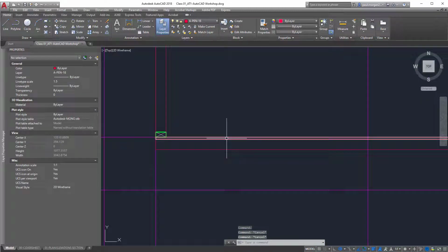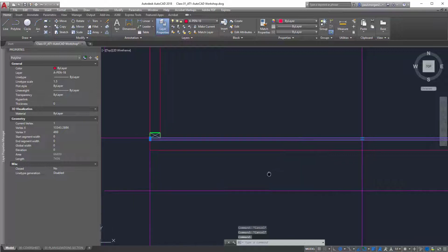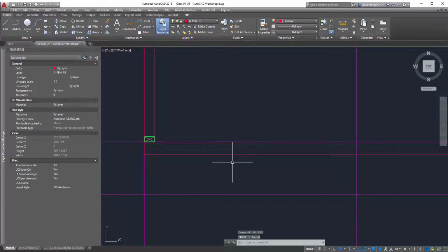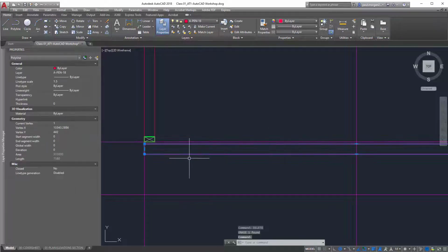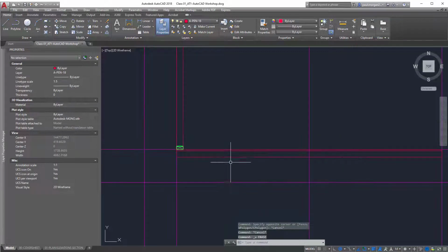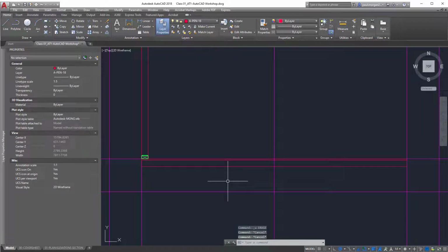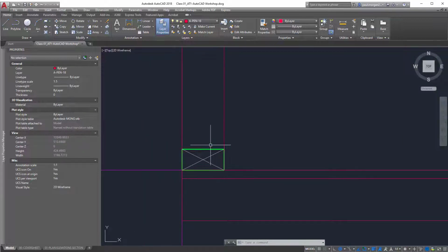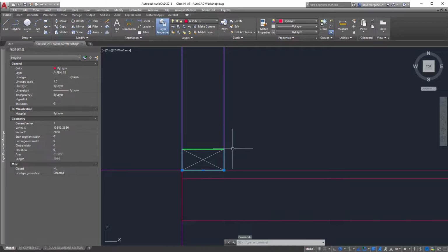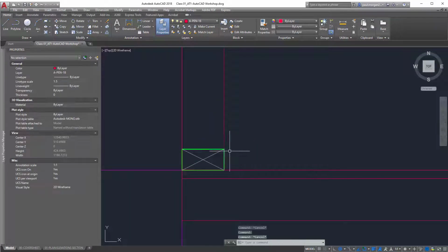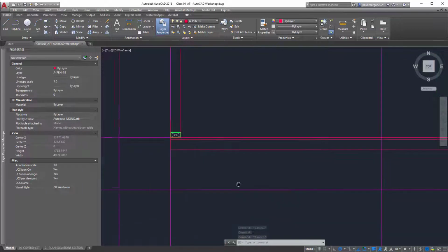But that's important though, because if at any point you need to hide one of these elements, like let's say I wanted to hide the tongue and groove flooring, I still want to see the top line of the joist underneath. If this wasn't a completed polyline, you wouldn't see that line there, and it just wouldn't be correct drafting manner. And just layering the same, if you've got two lines over the top of each other and they're on the same line weight, it's not going to matter at all. If there's two different line weights, it's always going to take the thicker line weight. That's why here with this timber stud, even though I've drawn the stud wall around it, it doesn't really matter because the pen 3.5 is thicker. It's going to go over the top of the pen 1.8.